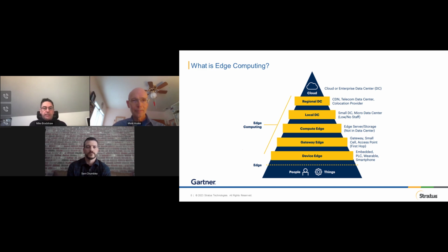Above that, they've got the next level as the data center, the local data center, should I say, where you'll find collection and control room, or data collection and control room systems like HMI and SCADA. The final tier within the model is the edge of this edge computing model, the regional data center. The regional data center is really the central hub that manages multiple sites, plants, and or control command centers. And as you can see, the scope of edge computing involves the majority of where the monitoring control of the plant or facility takes place.